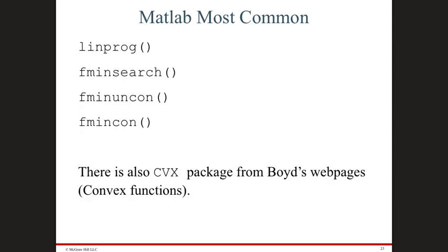Last but not least, these are some very important functions that you will use from MATLAB, particularly the last two. Okay? So there is one called fminunc. This solves problems that do not have constraints. And then the next one is fmincon. Minimize a function under certain constraints. And for each one of them, there's a format for how you pass the constraints, how you pass the function itself. And then these are using multiple techniques, and they use multiple variations of different techniques.